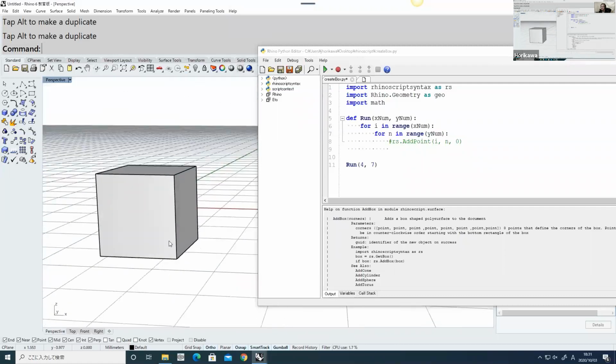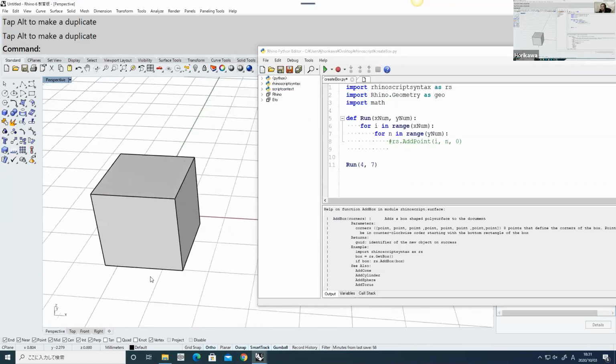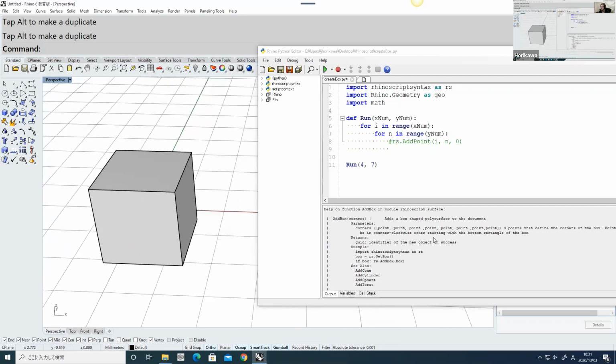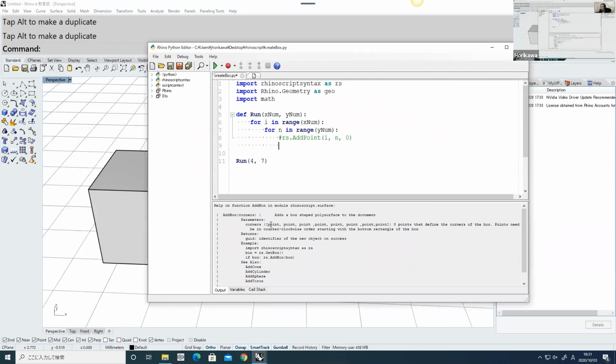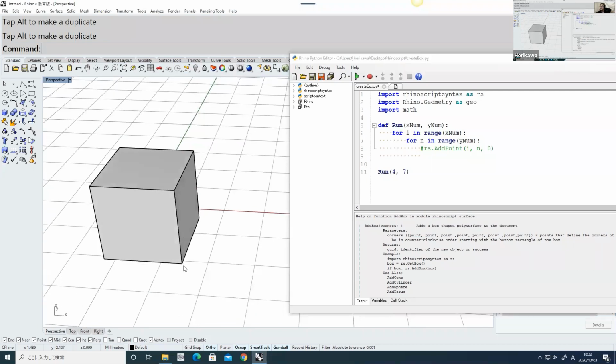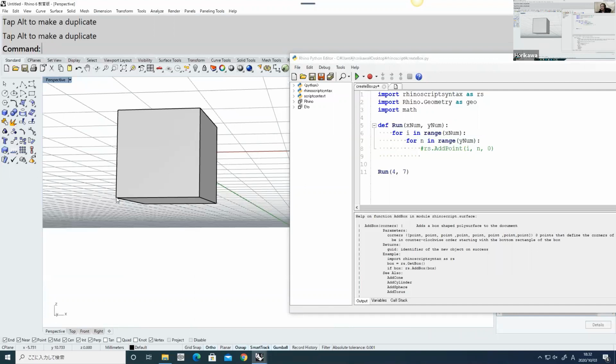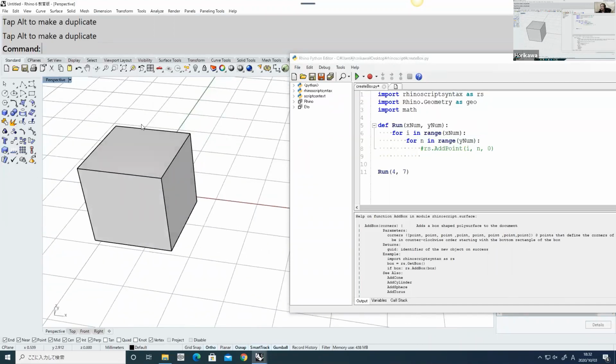If you think about that, there is some kind of rule we can think of for each point position. The bottom points and the top points can be divided into z equal to -1 or z equal to +1. Also we need to check the order we have to provide the points in, and it says counterclockwise order. So if we start the points from here, then counterclockwise, the first point is here, the second point should be here, the third point should be right here, and the fourth point should be right here. Then after that, going to the top, and it starts here, here, here, here.